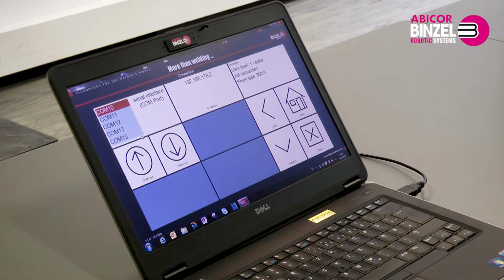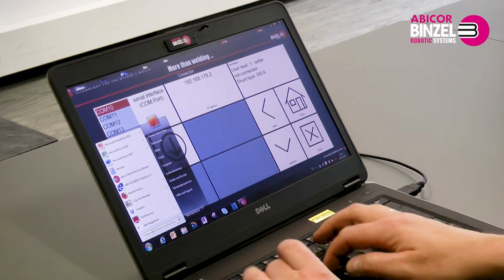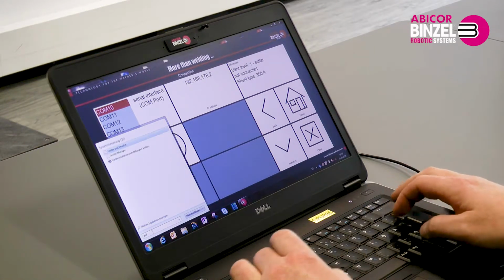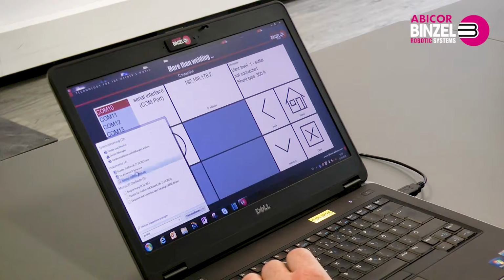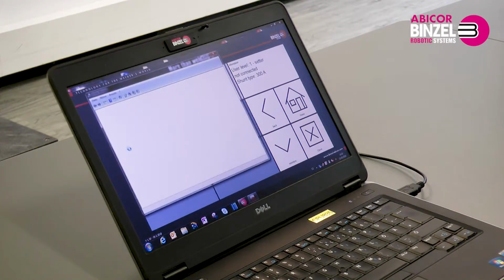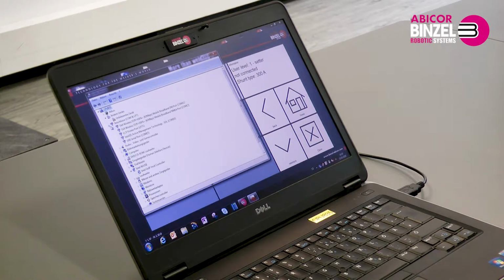These are located in the storage folder of the service software. If you are logged in as an installer, you must now set the correct Comport in the Settings, Software, Connections menu area, which connects the service software to the EWR2. To find out which is the correct Comport, please refer to the device manager of your computer. There you will see the different connections.